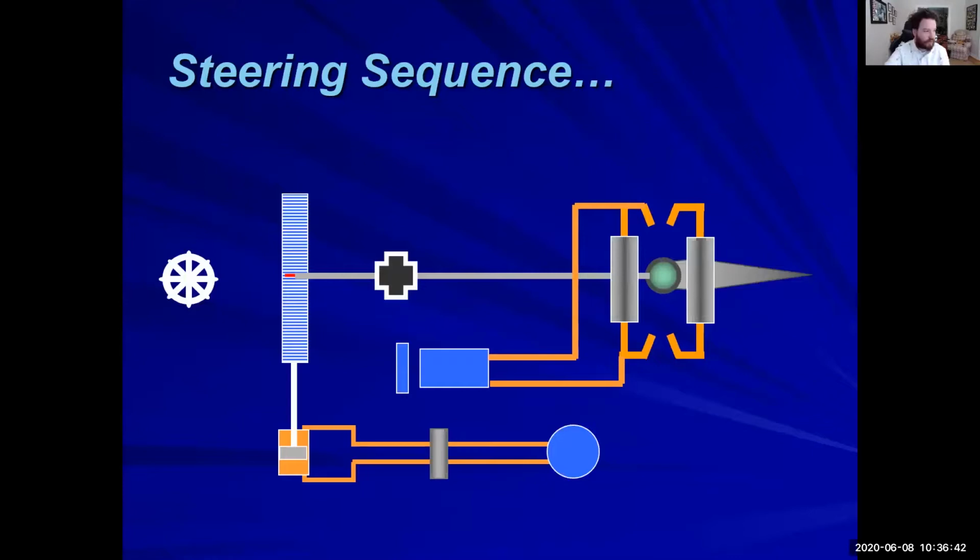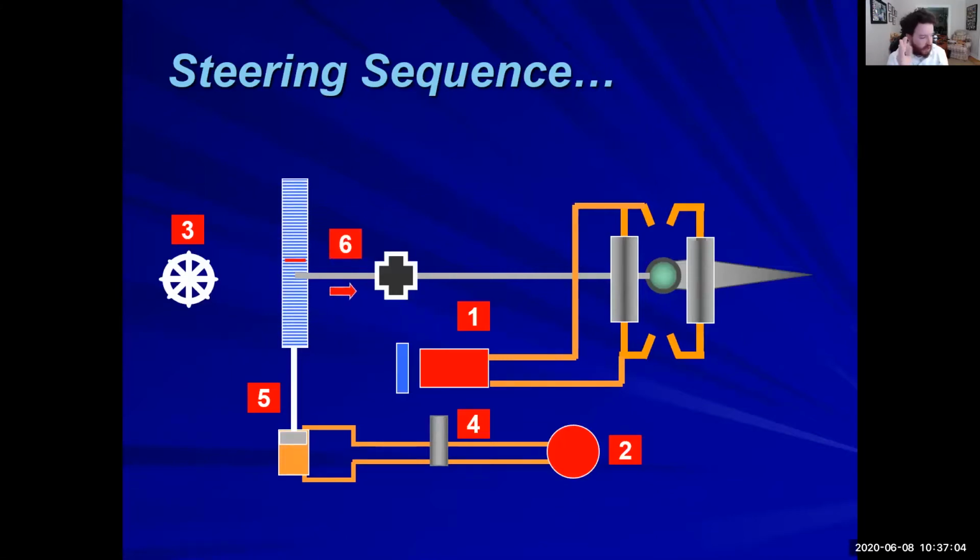So let's look at what we see on here. Number 1, the steering gear is running on an off stroke. The pilot pump is just running continuously. The helm turns to starboard. The shuttle valve moves, and we now have fluid flow. This is the first time we're actually going to have movement down there. That helm actually matches the rack. Once that happens, this shuttle valve goes back to its neutral position, and we have done our first input into the differential.